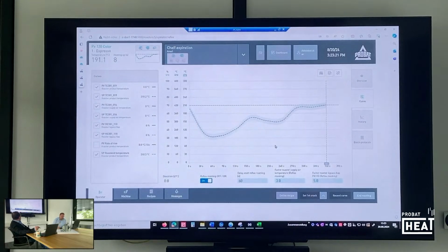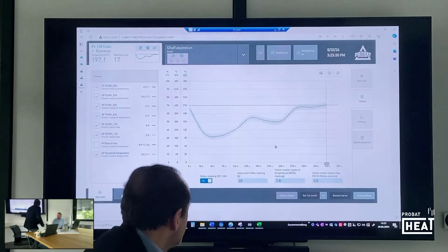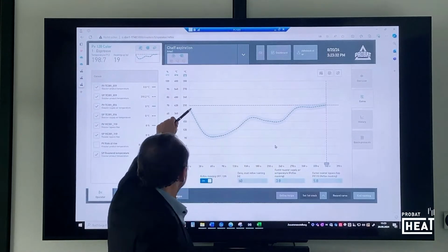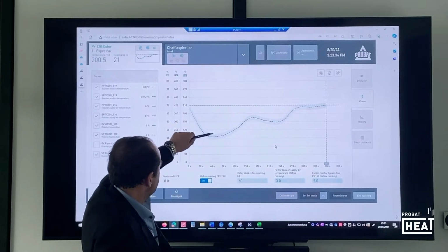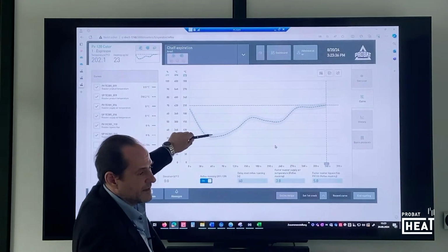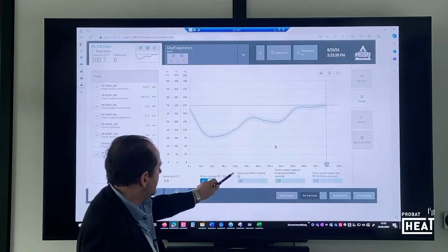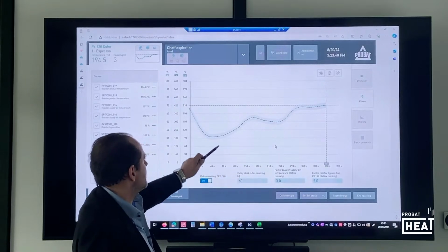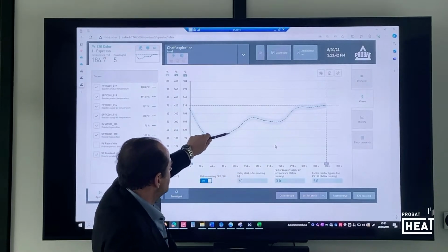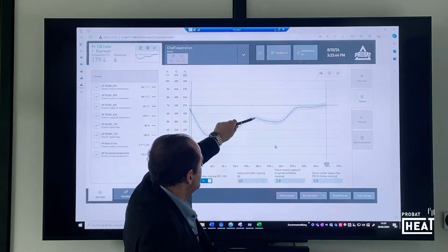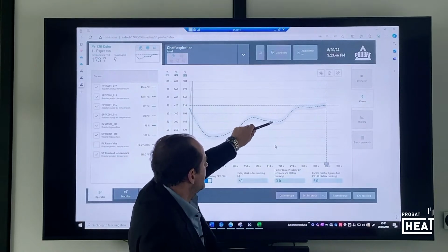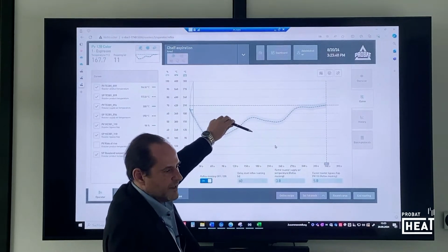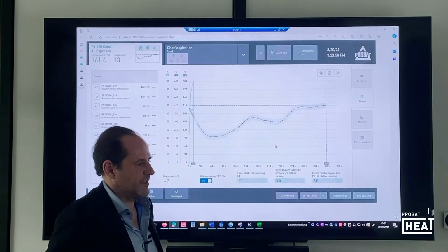So then we will see the limits of our roaster, and especially here, the drop down till the 60 seconds, I guess nothing will happen, because we have the delay start of the reflex roasting. And after this one we will see a strong heat up, and here we should see that the PR110 opens completely, so that we drop down the temperature, correct?